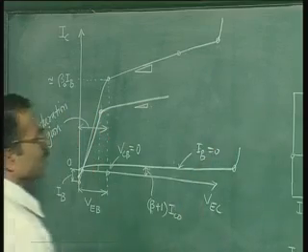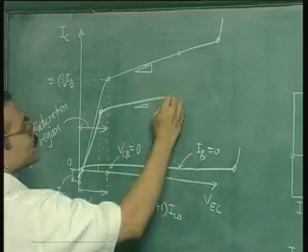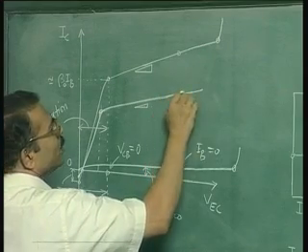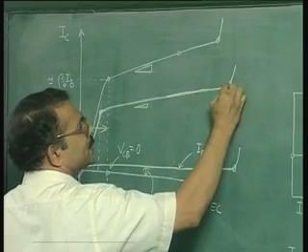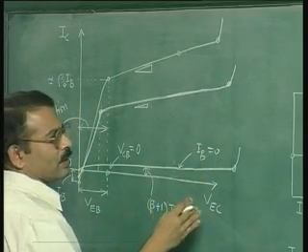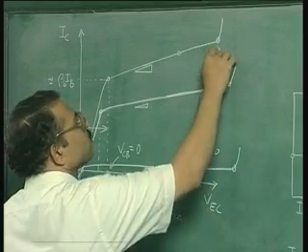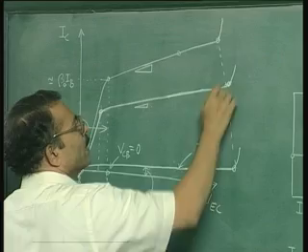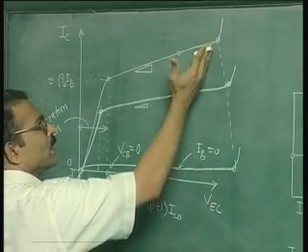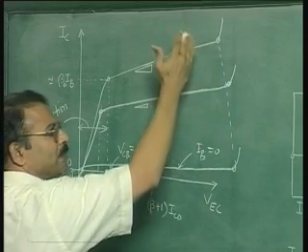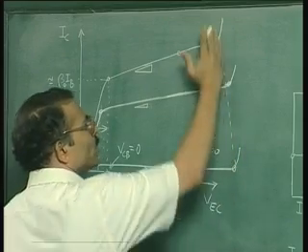So this is very important. You will find that for higher and higher values of IB, your slope will go on increasing, and then you will have a breakdown. Now, as we said earlier, and this point we will now explain, the breakdown voltage goes on decreasing as your IB increases from IB equal to 0. Of course it decreases, and then after some time it becomes constant and then it starts increasing again. So this change in the breakdown voltage with IB